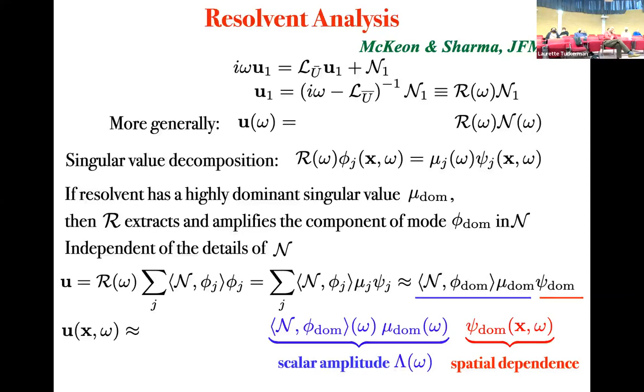But here, you act as though it's some unknown term, because how are you ever going to know it? You barely know the mean. How are you going to know U tilde dot grad U tilde minus the mean term? You're never going to know that, so you might as well treat it as an unknown.